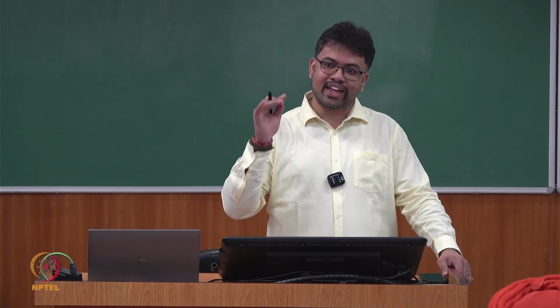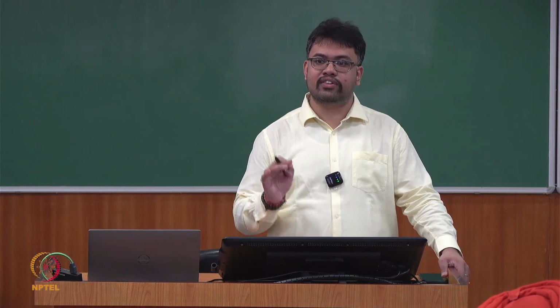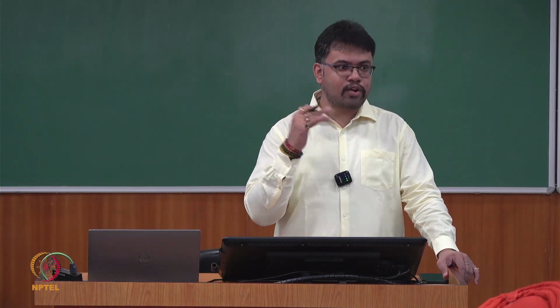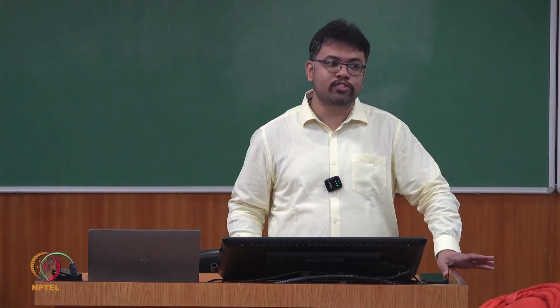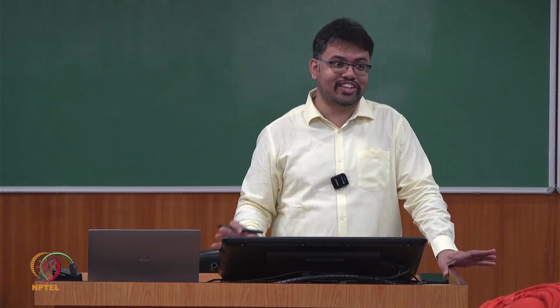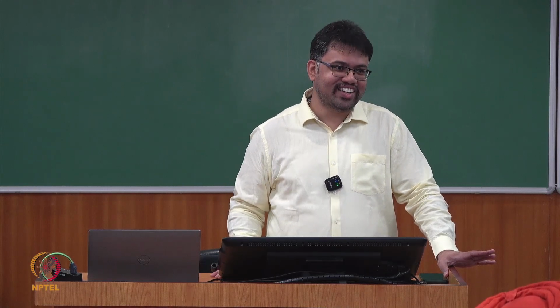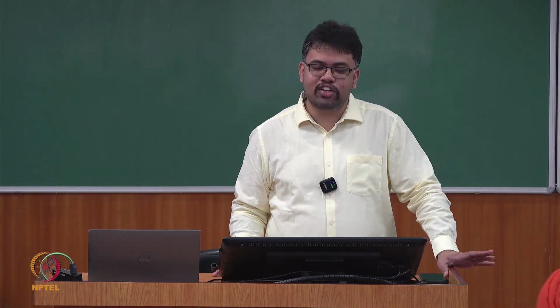But here we are not assuming. We are solving the differential equation, whatever it is coming. So that is not an approximation. So spectral element is not that approximation. Yeah, now if you say that the solution itself is the approximation, then I cannot say. But whatever is the exact solution of the differential equation, that tells that yes, this is the exact shape function for that.